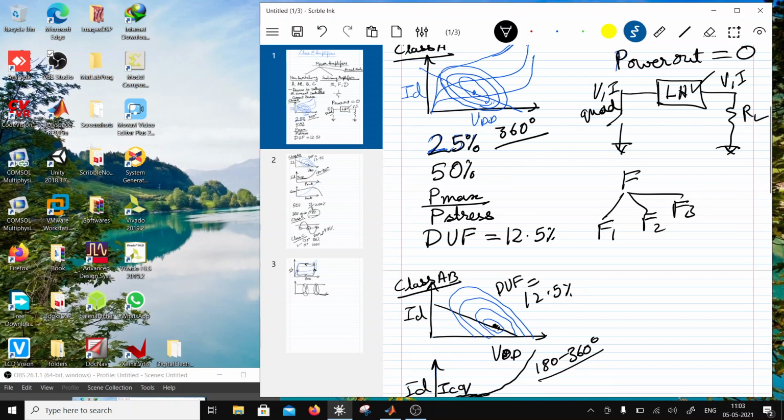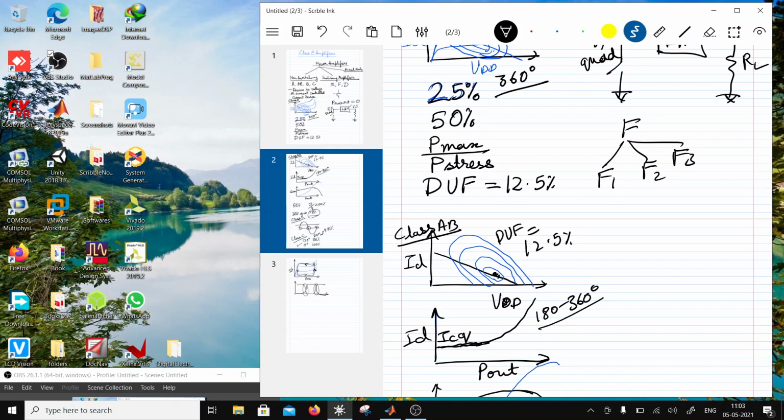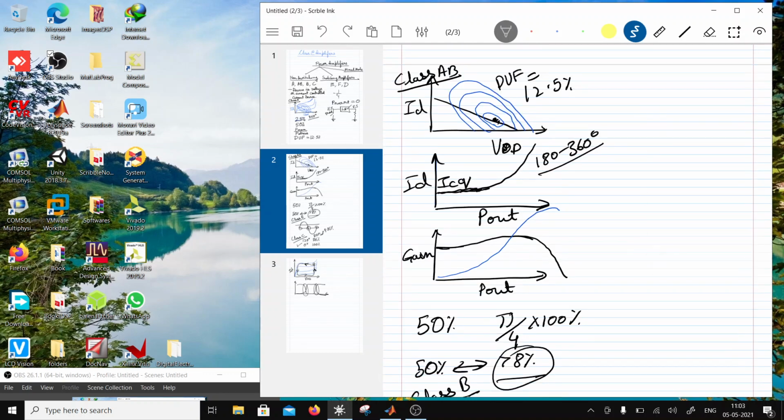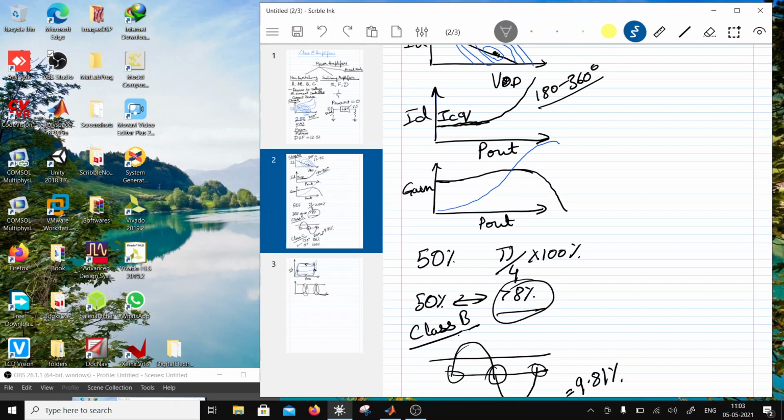Now there is something called maximally flat class F. A maximally flat class F is going to cause the voltage and current waveforms to flatten quickly. So basically, instead of taking this range of P out to flatten, if I can cause the flattening to be early. So how do I cause the flattening to be early?